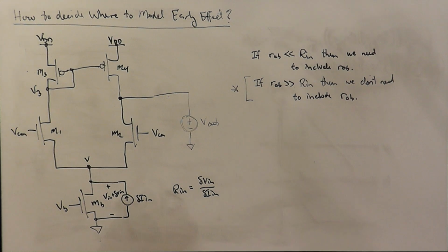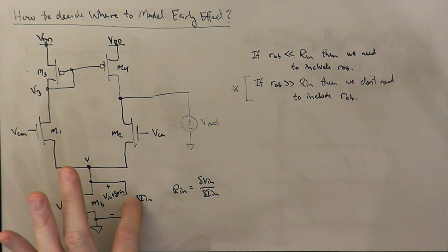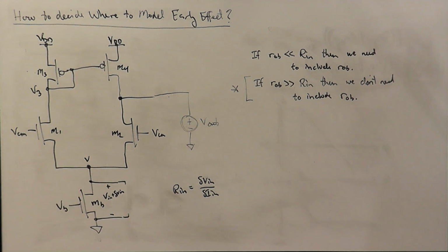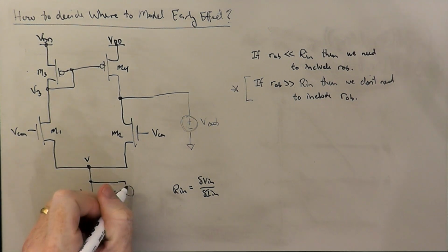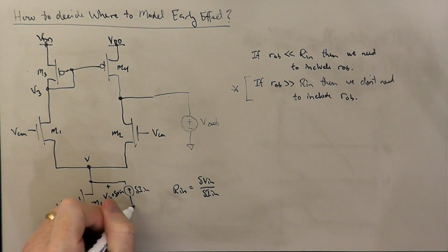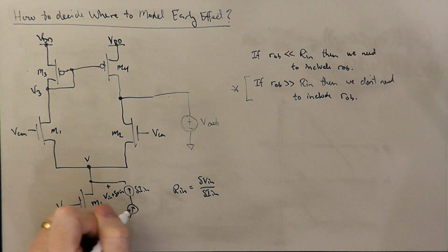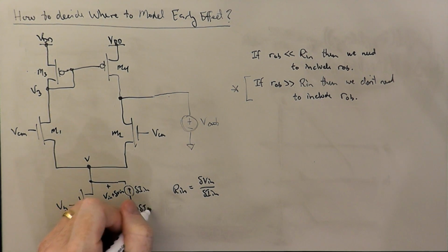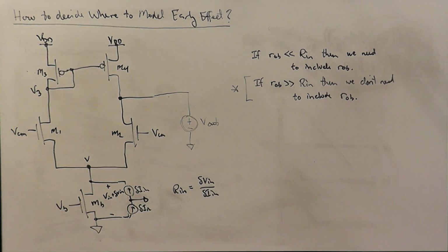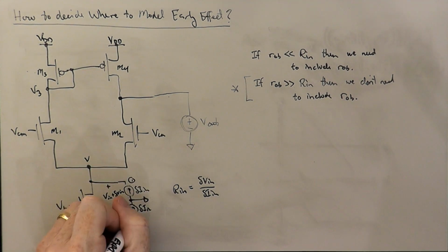Right, and so a convenient way of doing this is current source splitting and superposition. And so we would split the delta Iin into two replica sources, and then ground this intermediate node. This is source 1, let's say, and source 2.